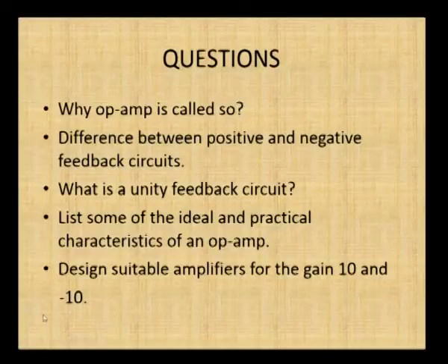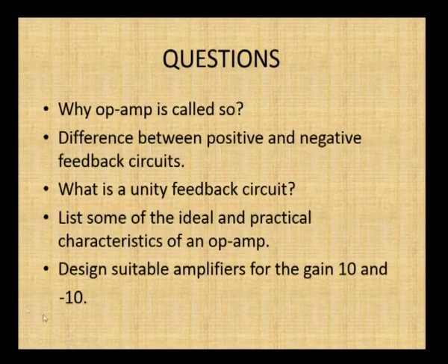From the gain itself, you have to know which is a non-inverting and which is an inverting amplifier. If the gain has a minus sign, you have to design a negative or inverting amplifier. If the gain is plus, then you have to design a non-inverting amplifier. The minus sign indicates 180 degrees out of phase with the input signal. The plus sign indicates the output is in phase with the input signal.